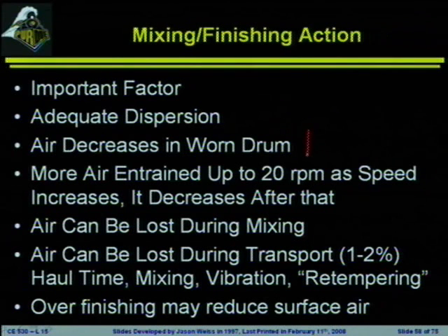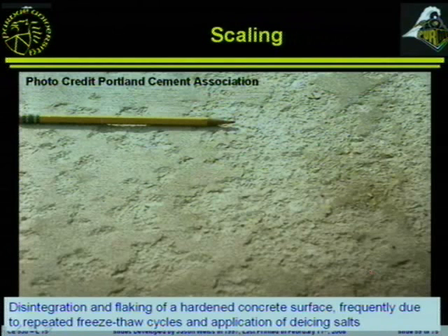If the drum on the truck is worn, you'll see it getting less mixing action, less air inside of the system. Air can be lost during the mixing process, as we talked about, and retempering can cause some problems. One of the problems that we can see that's specifically related to the surface of concrete is this idea of scaling.